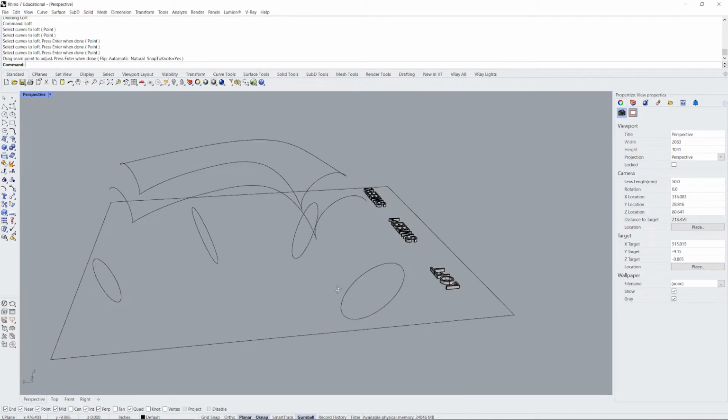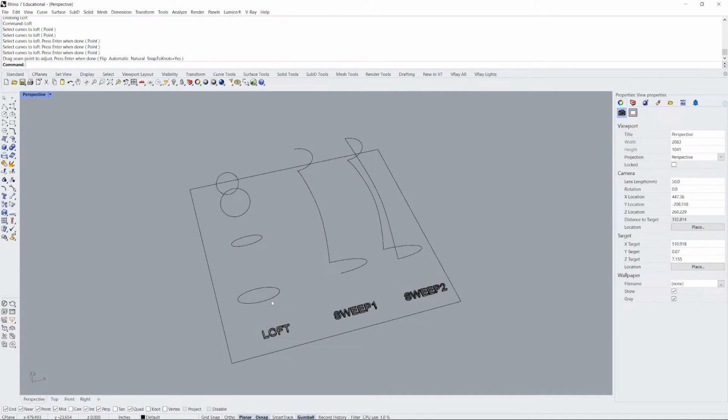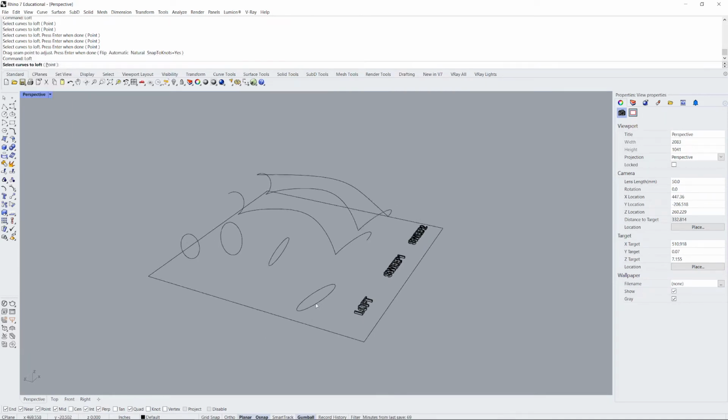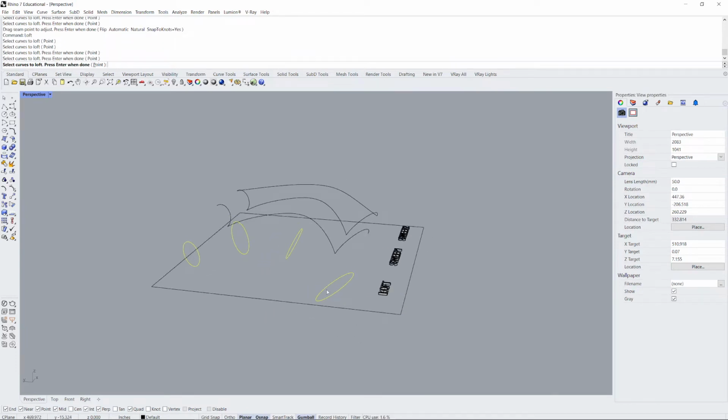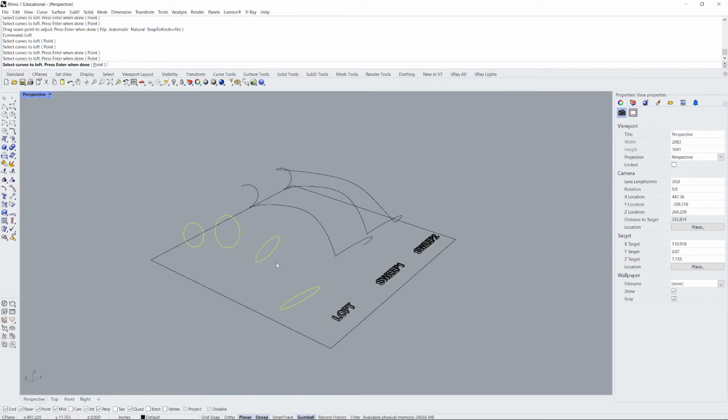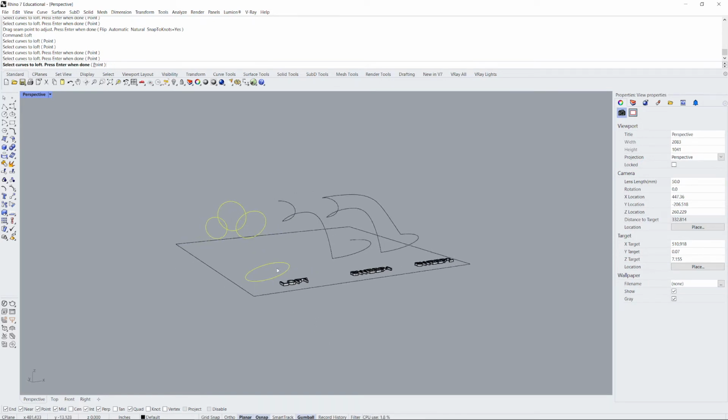So now, over here with the loft command, loft is a really great and powerful command. It does sort of an extrusion, but a sequenced extrusion where one curve leads into another and then into another and another if you want. So you can extrude a cube if you wanted to, or you can loft a cube if you wanted to, but really it's meant for more unique shapes like this and something that sweeps or bends over as opposed to something that does something super linear.